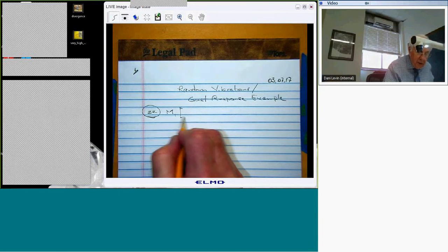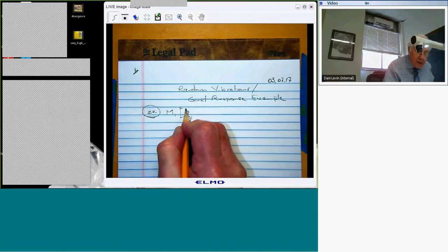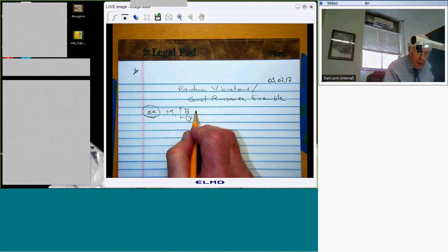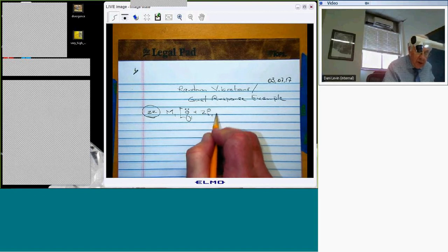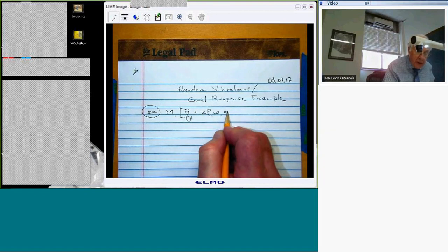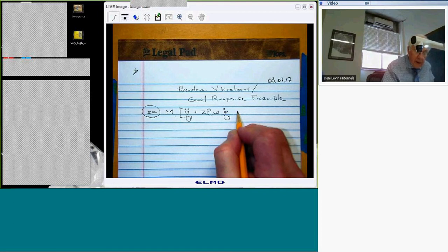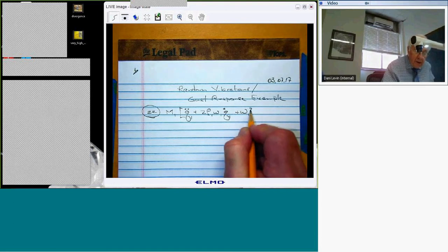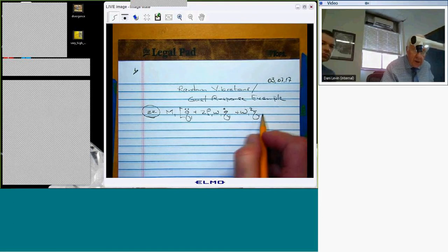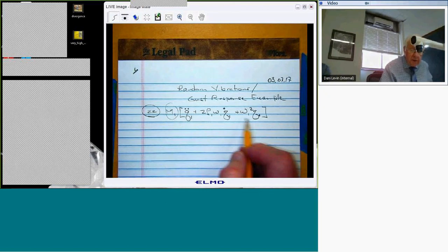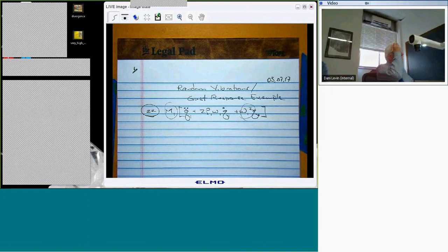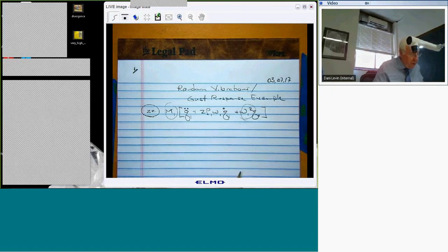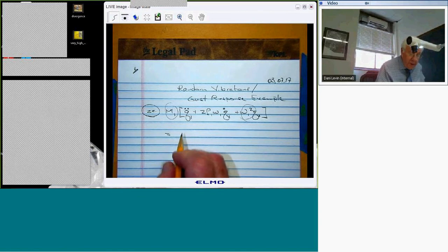This is for one mode whose generalized coordinate is Q1. We arbitrarily but reasonably put in a structural damping term, and then we argued that this linear stiffness term can always be expressed as the generalized mass times the square of the natural frequency times the coordinate. And then we're using piston theory aerodynamics, which simplifies our aerodynamic model.